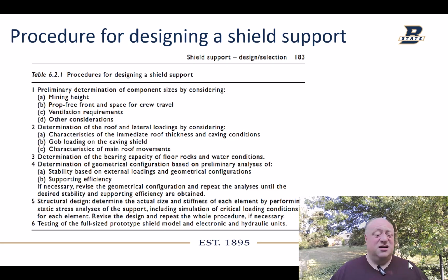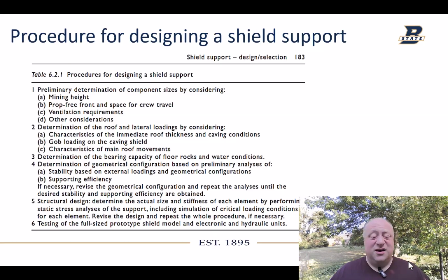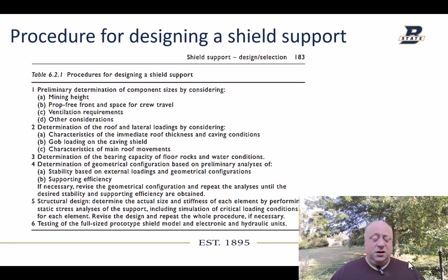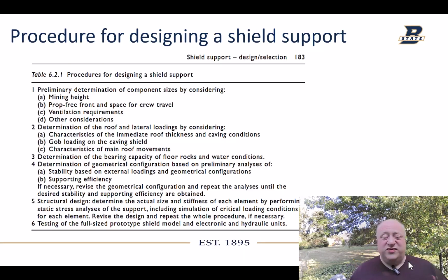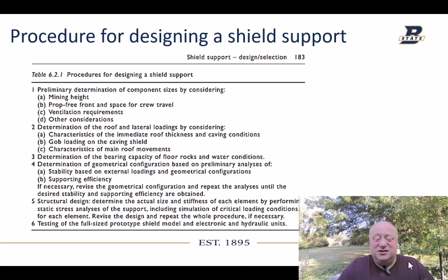4 is the geometrical configuration, based on the analysis of stability, right? So the external loadings and the supporting efficiency. You can use those to determine what this shield configuration actually needs to be, the components of the shield. And if necessary, you can revise that and repeat the analysis until your desired conditions are met. 5 is structural design, determining the actual size and stiffness of each element by performing static stress analysis,